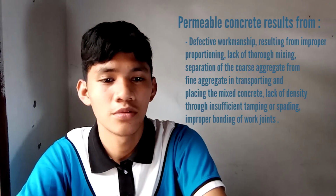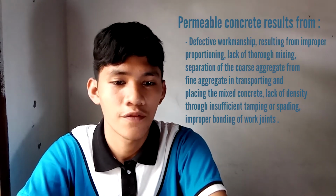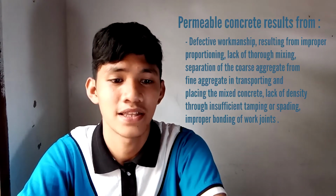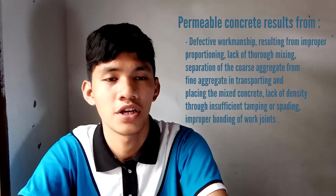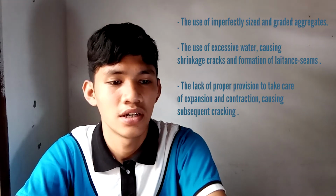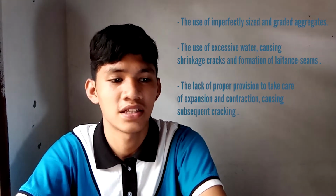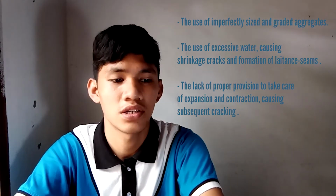Of course, we do not want to have a permeable concrete, but how can we get a permeable concrete? Permeable concrete results from defective workmanship, resulting from improper proportioning, lack of thorough mixing, separation of the coarse aggregate from fine aggregate in transporting and placing the mixed concrete, lack of density through insufficient tamping or spading, improper bonding of work joints, the use of imperfectly sized and graded aggregates, the use of excessive water causing shrinkage cracks and formation of laitance seams, and the lack of proper provision to take care of expansion and contraction, causing subsequent cracking.